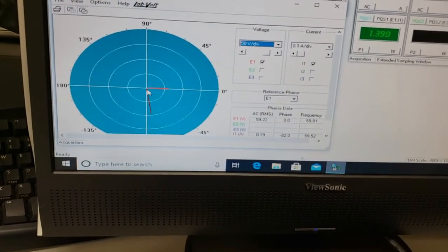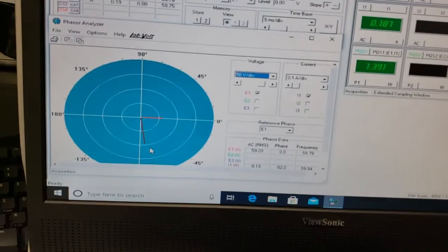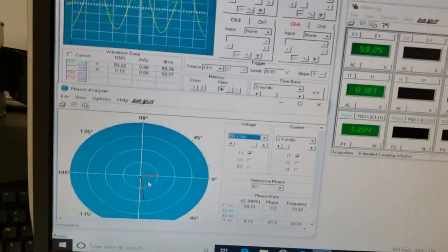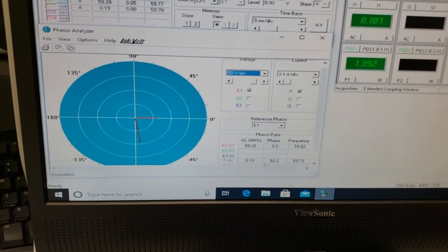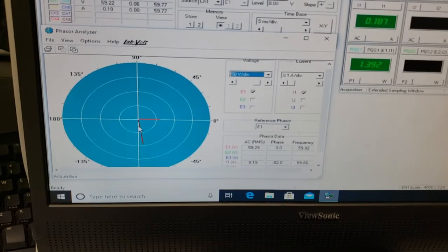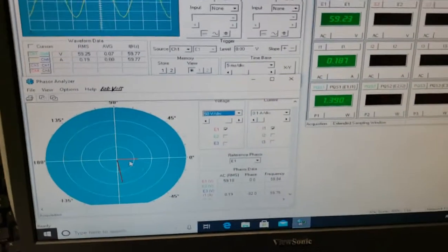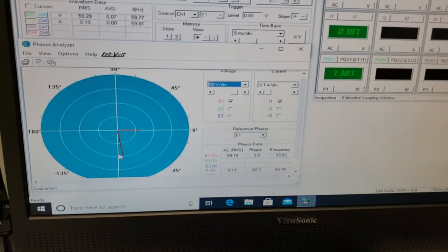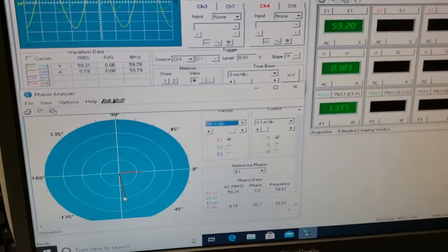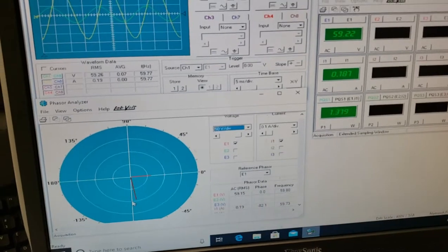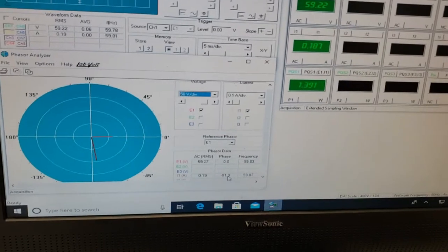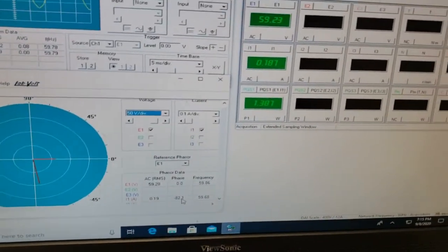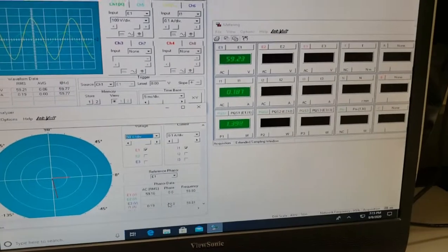This is more easily expressed over here. This is the voltage waveform, and this is the current one. For a purely inductive load, we should expect that voltage and current are 90 degrees out of phase, and the voltage should lead. And indeed, that is almost the case here. We have an 82-degree phase difference, and the current lags the voltage waveform by 82 degrees, which means there's about 8 degrees to go. This disparity between the ideal case and this actual case is probably because of the resistive component of the inductive load. But okay, so that's with the inductive load.